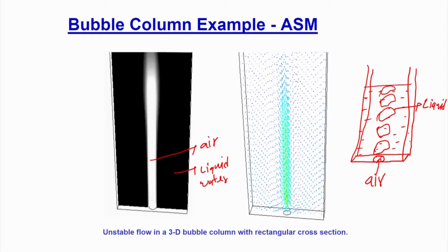We are also able to solve the drift velocity equation, and we are coupling it with the slip velocities too. So, you can solve the relative motion. Then we have also calculated the velocity of the water. Why have we not plotted the velocity of air? Because the velocity of the air will be only at the center and it will be moving upward. So, we have tried to show the velocity of the water. This is the water velocity, and these simulations are being done in ANSYS Fluent.